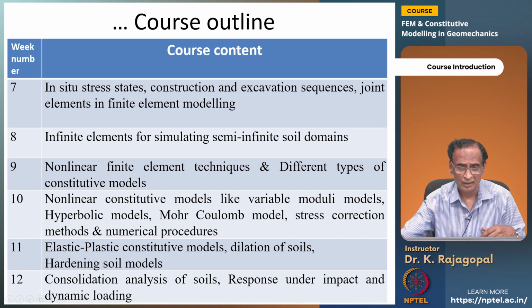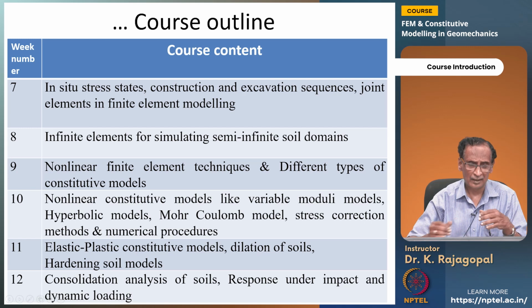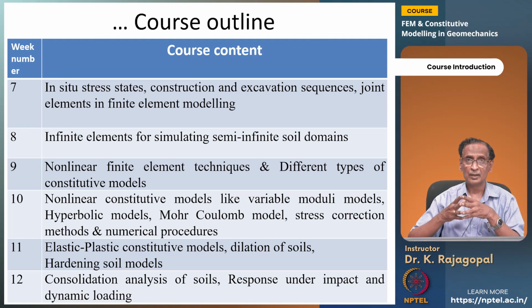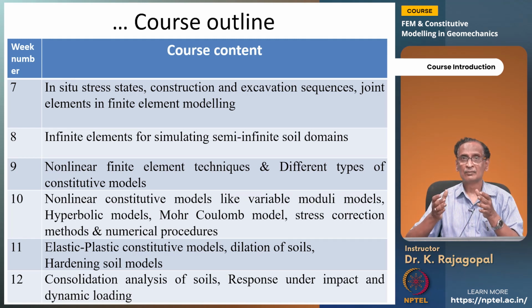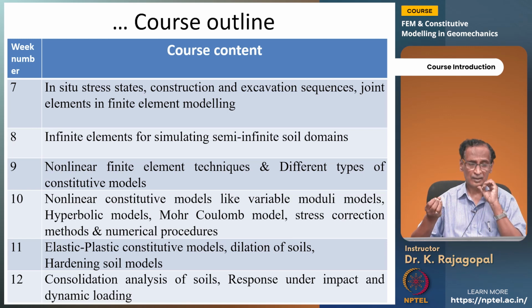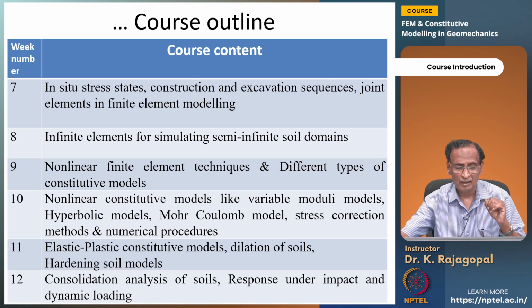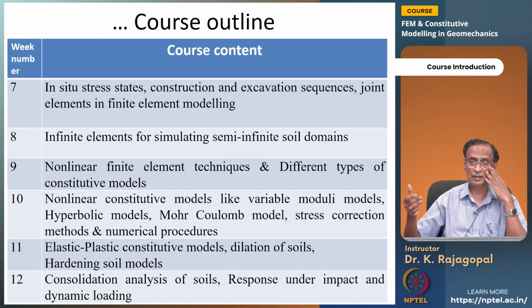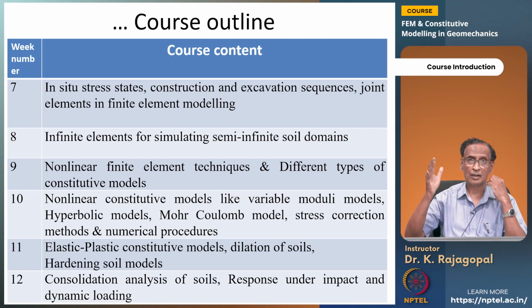Then when it comes to geotechnical engineering, we have to take care of in situ stresses, that is the pre-existing geological stresses, because sometimes our entire response might be dependent on the in situ stress states. Like sometimes our initial earth pressures could be very high, especially if we are dealing with any over consolidated clay, and in such cases if you make any excavation, you have to expect significant release of stresses that might cause problems to our neighboring buildings or our own support structures.